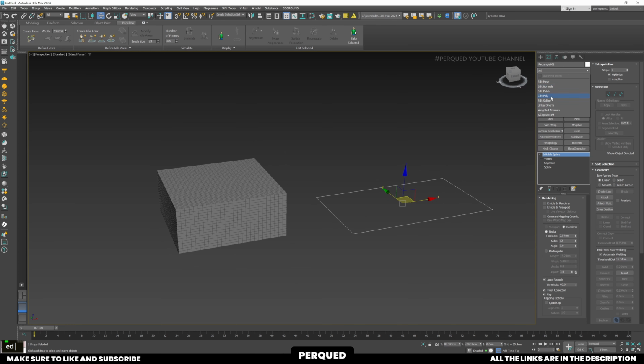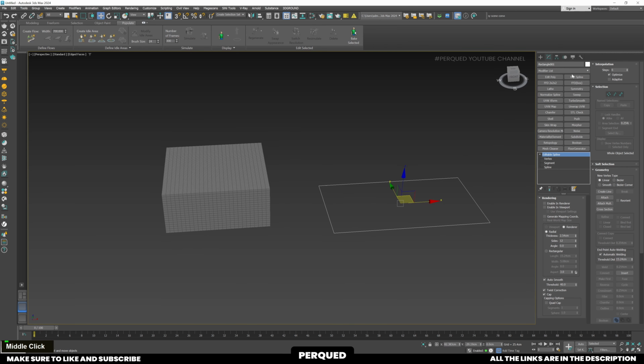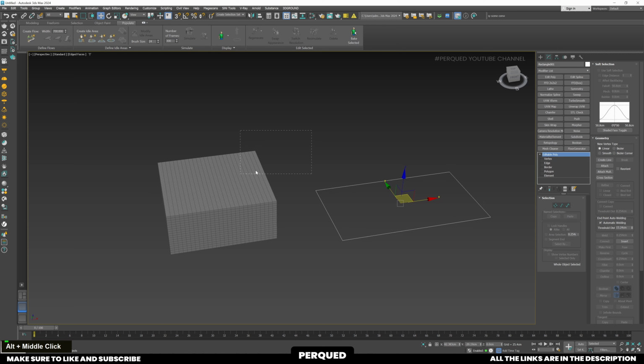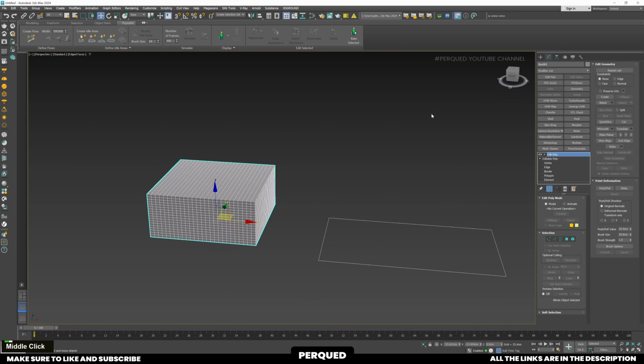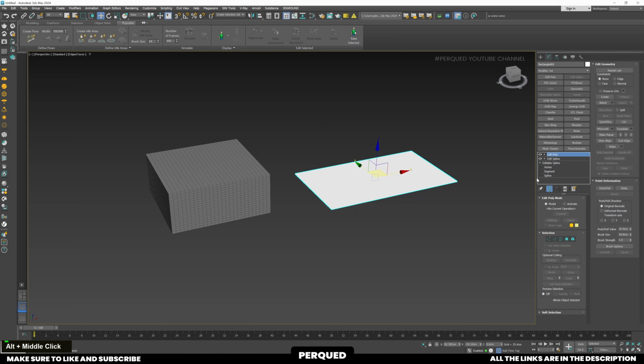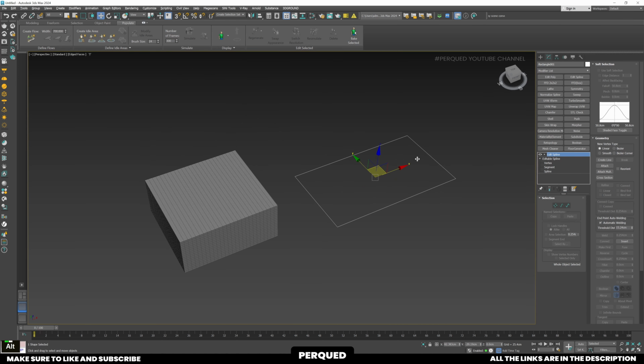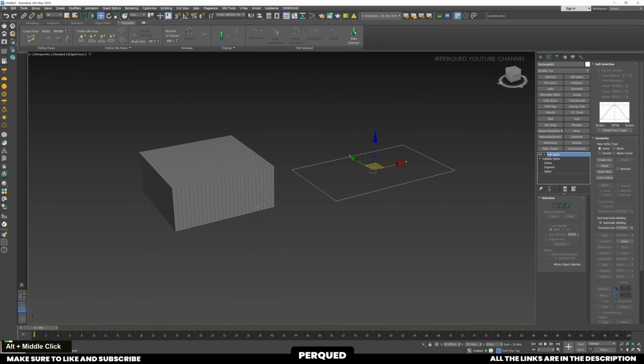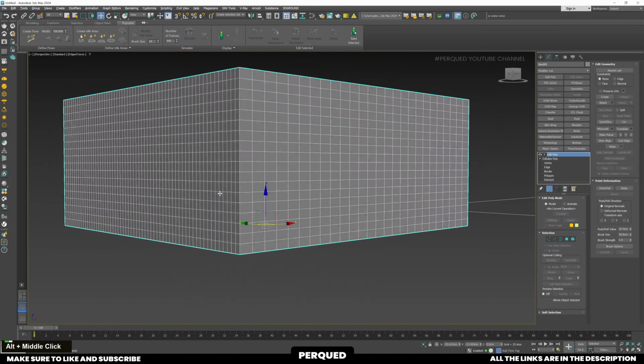What this will do is that it'll add Editable Poly or Editable Spline as extra modifiers. Both have their own advantages and disadvantages. The more you use 3ds Max, the more you're going to know about it by yourself. Now these Editable Poly or Editable Spline modifiers are used to make further adjustments to the geometry and shapes.